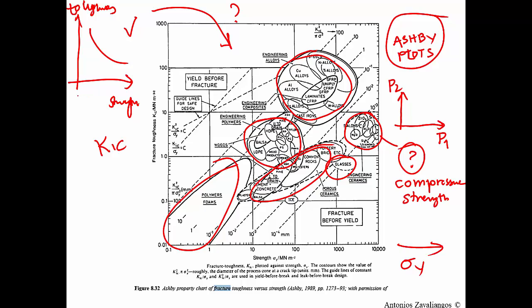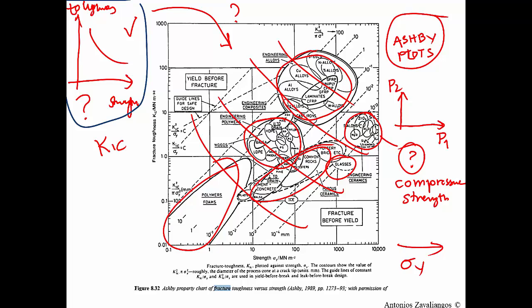Do you really understand what that means? Why don't we see lines like this here? The answer is really that this kind of relationship does not hold across classes of materials, but it holds for a given material, and the differences in properties are achieved through heat treatment, changing of the microstructure.